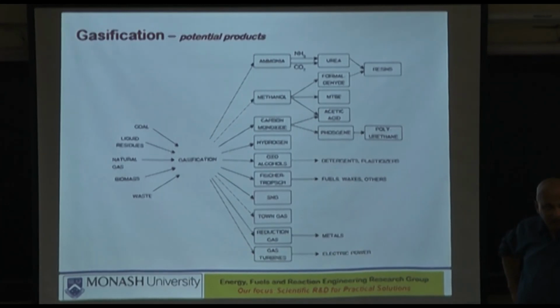For example, for methanol, you need 1:3. For some other reactions, you may need 1:4, carbon monoxide and hydrogen. So you need to increase the proportion of hydrogen. And how can you do it? Through the shift reactor, you can get the hydrogen. The question is, coal has only 4–5% hydrogen to start with, right? That is what we said right at the beginning. So if you want more hydrogen after gasification, where will it come from?